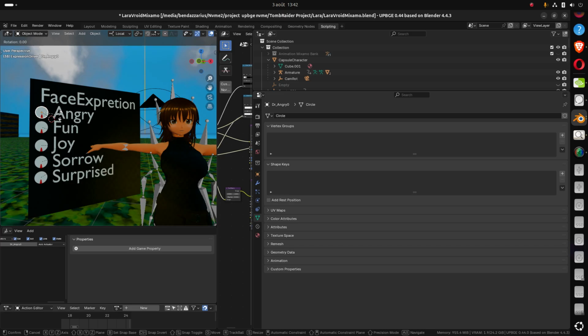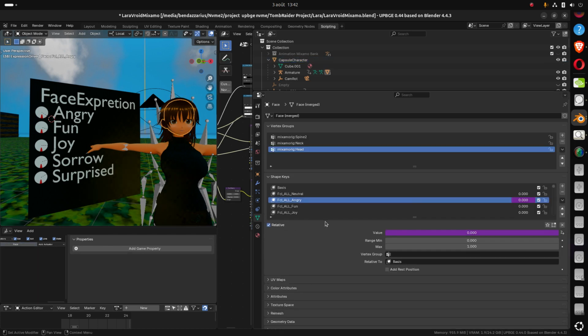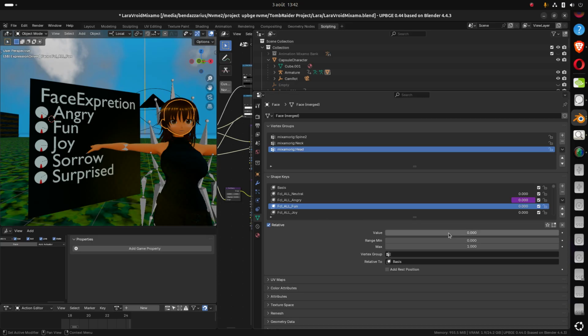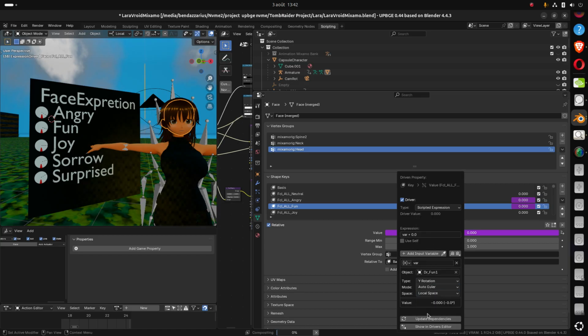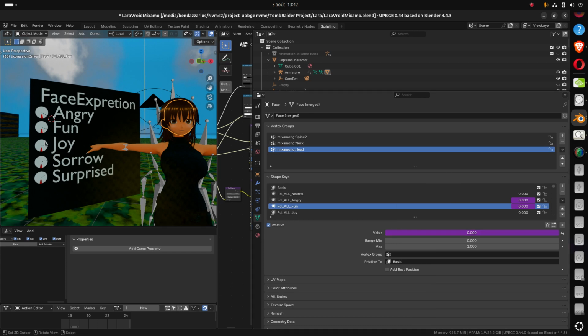A driver extrapolates a value up to 60 degrees when a rotation is chosen. This means that if we go beyond 60 degrees, it will cause an issue. Therefore, in our logic node, we will need to create rules to ensure that the button cannot rotate beyond 60 degrees. I'm going to assign each driver for each expression in the same way, using the same values.